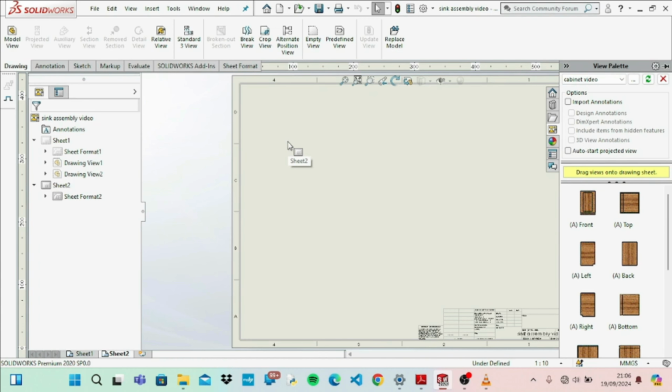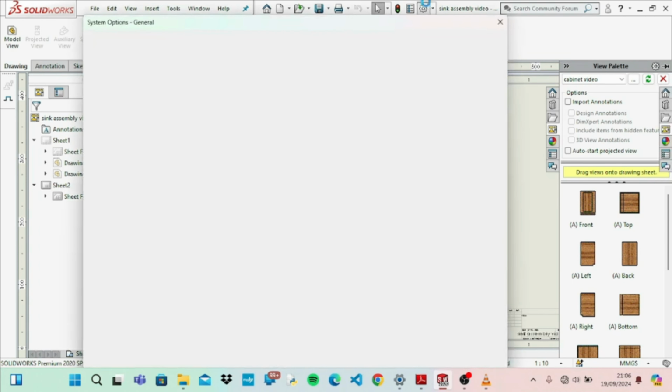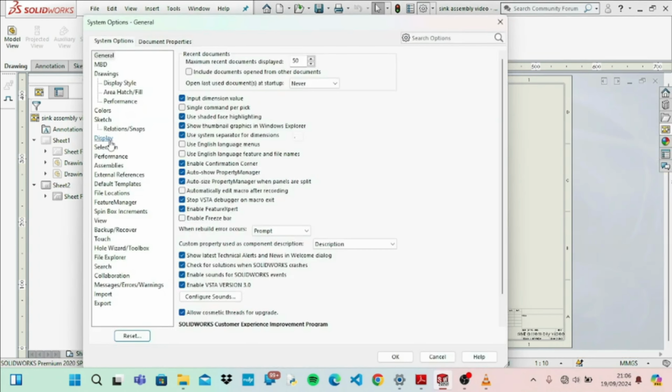In first angle projection, the front view is displayed on the upper left, and in third angle projection, the front view is displayed at the lower left. SolidWorks uses first angle projection in this drawing. However, it is possible to change it to third angle projection.